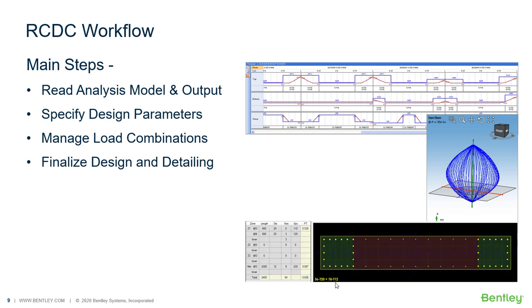Or for a shear wall, you can review the arrangement, how the bars look, check the importance of that, maybe finalize the length of the boundary element differently. You can perform multiple iterations or try different combinations, and once you are comfortable, you finalize the arrangement.